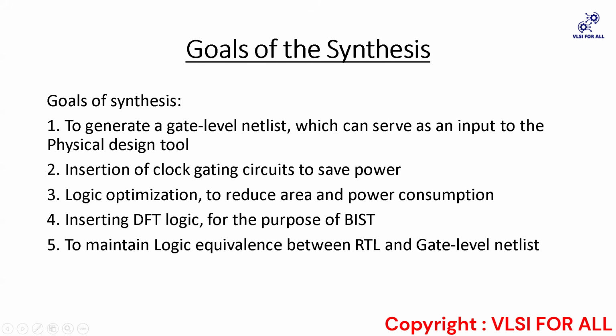So I think you already know the clock gating technique, right? It is a technique which is used to save power. Whenever our circuit is in use, only then the clock signal is given to that circuit. Till then it is off, it is not given, which saves a lot of power. Our power gets optimized due to the clock gating technique.